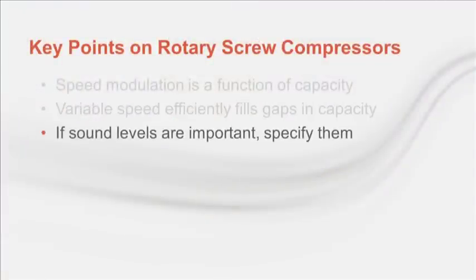Today, our rotary chillers have better acoustic performance than older generations. Full load sound levels are around 7 to 10 decibels lower than rotary chillers that are less than 10 years old. Meanwhile, some competitor centrifugal chillers in the last 10 years have substantially increased their full load sound levels, due in part to much higher speeds at full lift or full load. If low or specific sound levels are needed, specify the performance at full load or worst case.